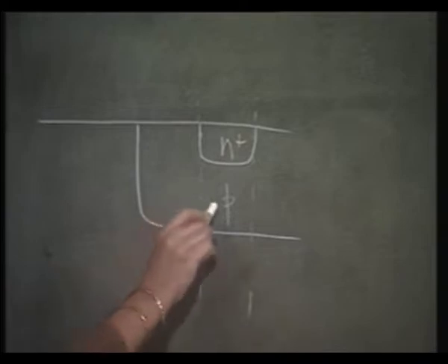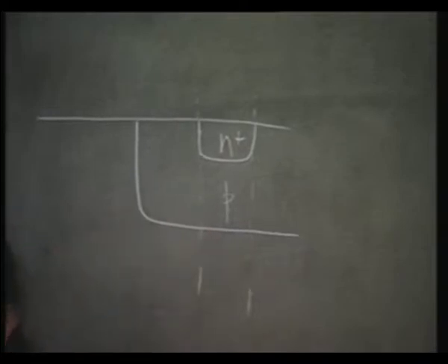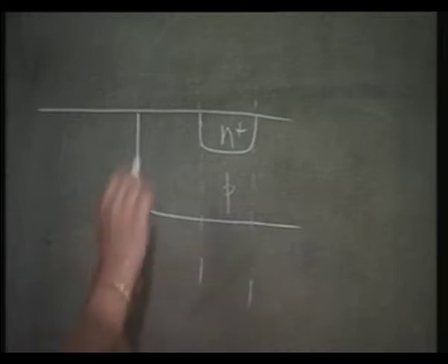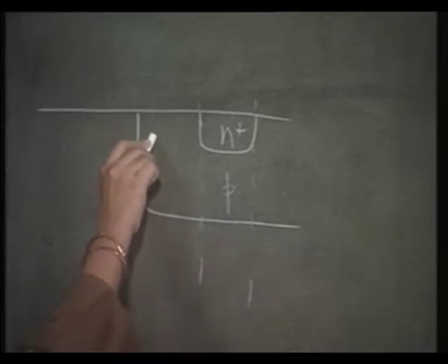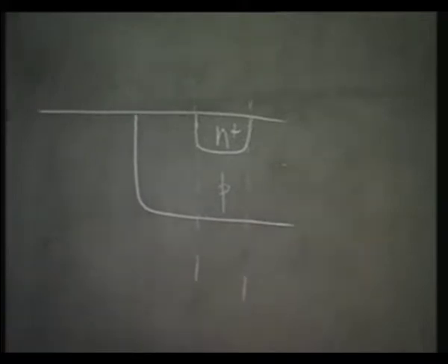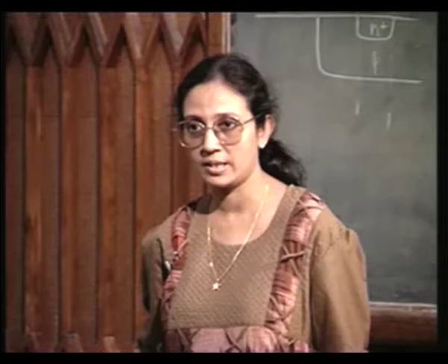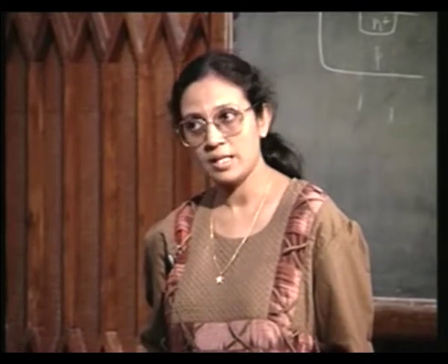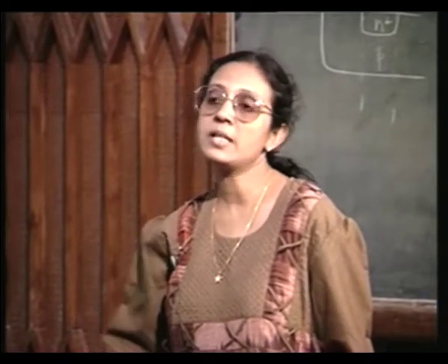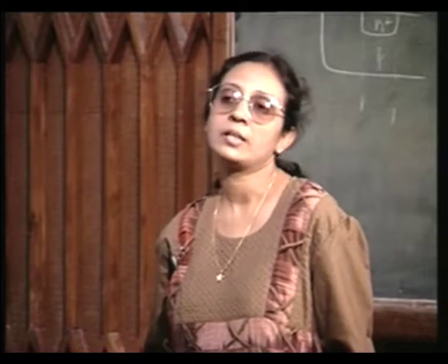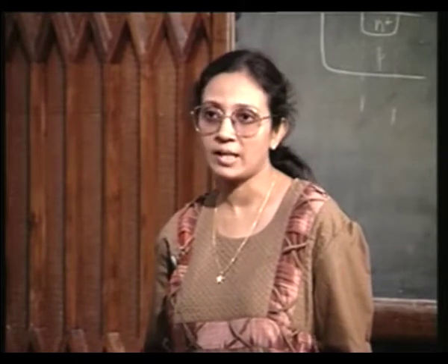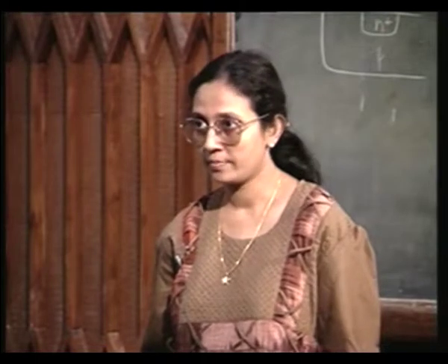So, this base doping is automatically fixed by the gain of the transistor, but you want to make these regions highly doped, which are extrinsic base. At the same time, notice that the extrinsic base must be separated from the emitter, otherwise you will have an N plus P plus junction there, right. So, again you see, you need to have the extrinsic base self aligned to the emitter.